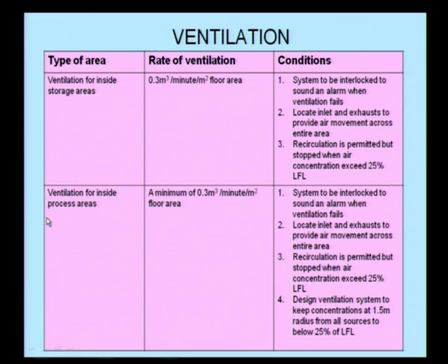You may wonder why the guidelines for ventilation for storage area and process area is almost similar. It is because inventory kept in the storage area can also be highly probable for explosion or fire accidents, or the chemical process can also be highly flammable. Therefore, looking into the fire and explosion possibilities, whether it is a storage area or a process area, NFPA looks at this in a global view that the rate of ventilation suggested for both the segments are appropriately equal.